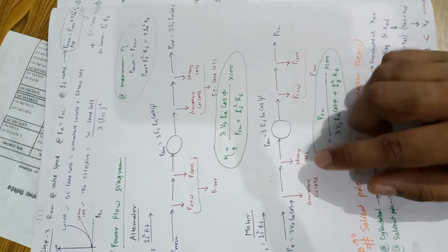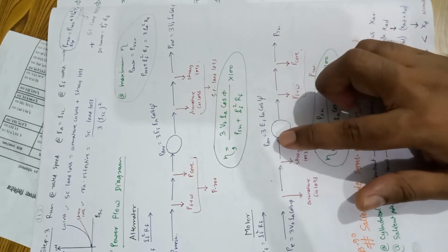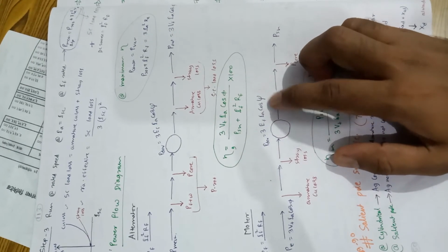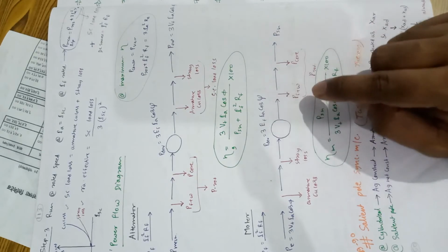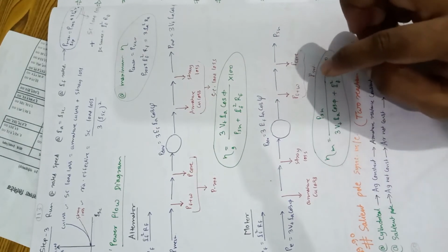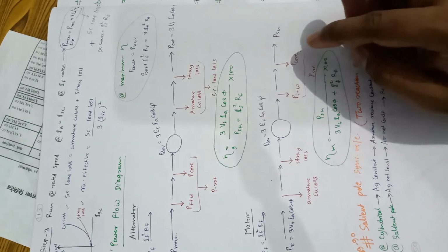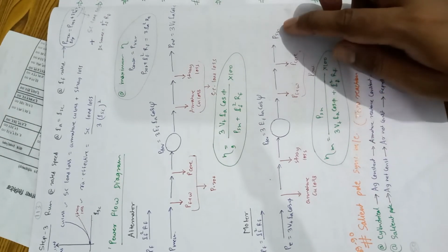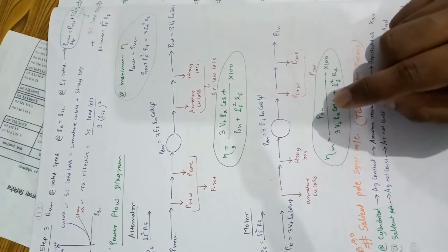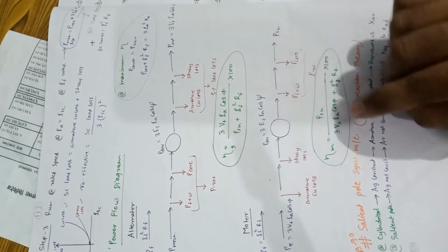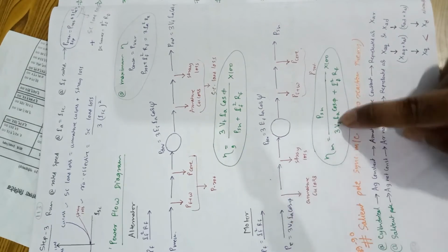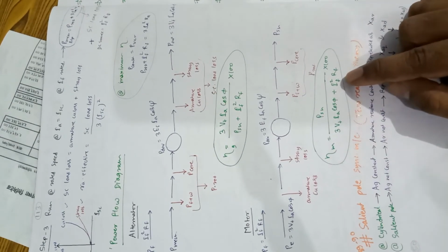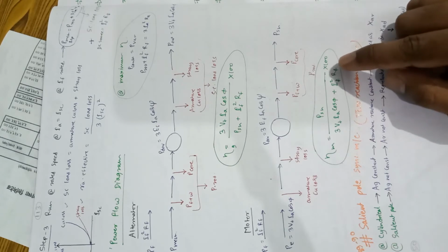After giving these two, the losses will be armature copper loss and stray load loss. After this we get developed power, 3 EF IA cos psi, where psi is the angle between EF and IA. After that we get friction windage loss plus core loss, that is rotational loss. Then finally we get shaft power. And efficiency is output upon input, output is PSH and input is 3 VT IA cos phi plus IF square RF, into 100.